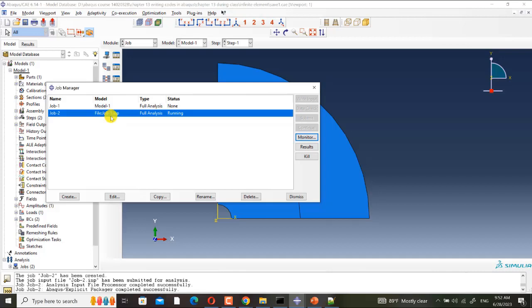Most of the students make this mistake. First, they edit the IMP file and add their own keywords and then import it again. This is wrong because a CAE model is always translated to an IMP file correctly, but an IMP file is not always translated to a CAE model correctly.